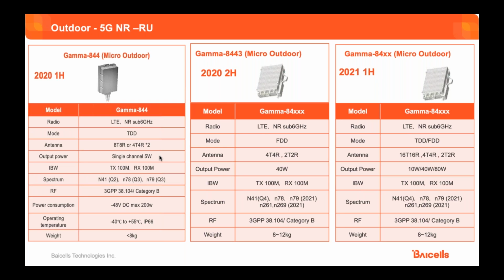Now the difference between 5G and 4G, in LTE, the maximum bandwidth that you can work with is 20. According to the specs it is 5, 10, 15, and 20. But with 5G, you take it to 100, and you even take it all the way up to 800 megahertz of bandwidth when we talk about millimeter wave. That's how you actually pack more data. You open up the bandwidth, and 5G specs is doing this.